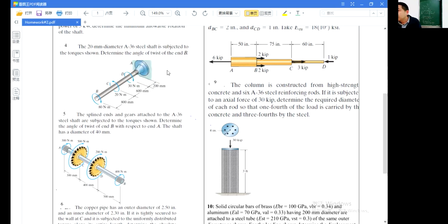So minus 80 plus 80. You can write positive, negative, positive. Find T is minus 60. But you have to assume the positive direction as in mechanics of materials. It's the same convention: you always assume it points out of the section.